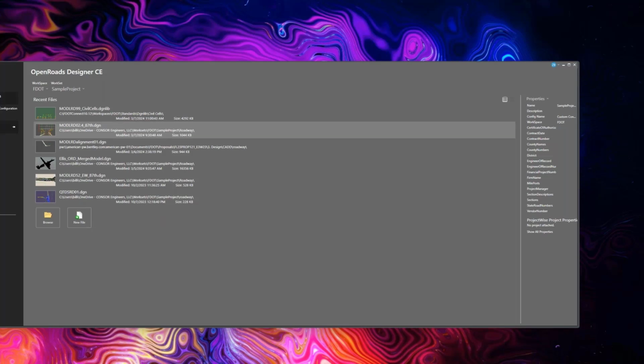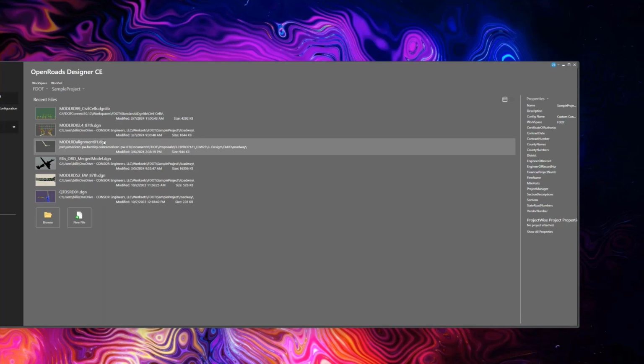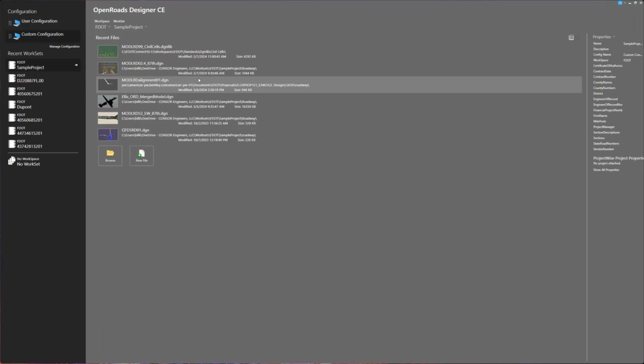Have you attempted to use civil cells for guardrail approach and trailing ends? I haven't really needed to use that because a lot of times when I do that, I just have a template that is like a barrier, and kind of similar to what I would do with the curb there, dropping everything down to make it match. Usually you have that 25-foot transition from the full height barrier down to the curb.